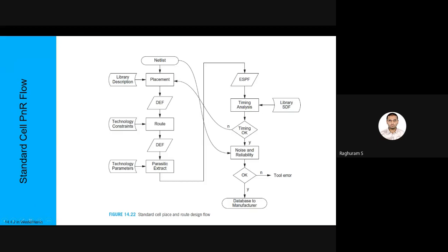It is the metal interconnections, and whenever you have metal interconnections of a certain length, we can extract the resistance R equal to rho into L by A. A was available from the beginning. Everybody knew the area of cross section, but nobody knew the length. Everybody knew rho because the material is fixed, it's generally copper, and L is the actual length of the interconnect based on the placement and the routing. So that was not available before, it is available at this time.